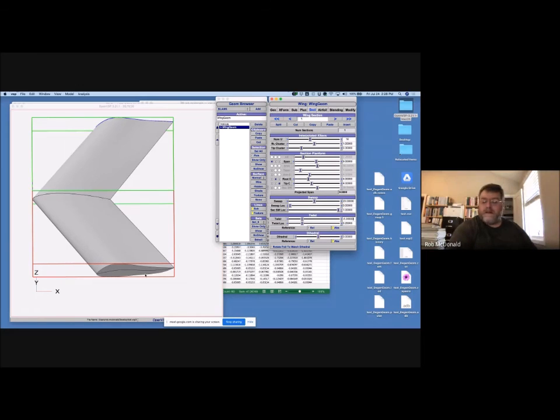So you're going to start with less destabilizing airfoils. When I was an undergrad, back when I was in college, my senior design team designed a flying wing. We didn't have VSP, we didn't have a lot of sophisticated tools, and we were faced with the same thing. I was the one doing this part of the design. And so we had this choice: are we going to use twist and sweep? Or twist and reflexed airfoils? Or sweep and reflexed airfoils? Or both reflexed airfoils and twist? What we decided at the time was that it was harder for our tools to predict the detailed moment of the airfoil and the reflex influence. And we were less confident about our ability to build, because this was something we were going to build and fly with our own hands and not much skill. So it was harder for us to build something that really got the reflex perfect.